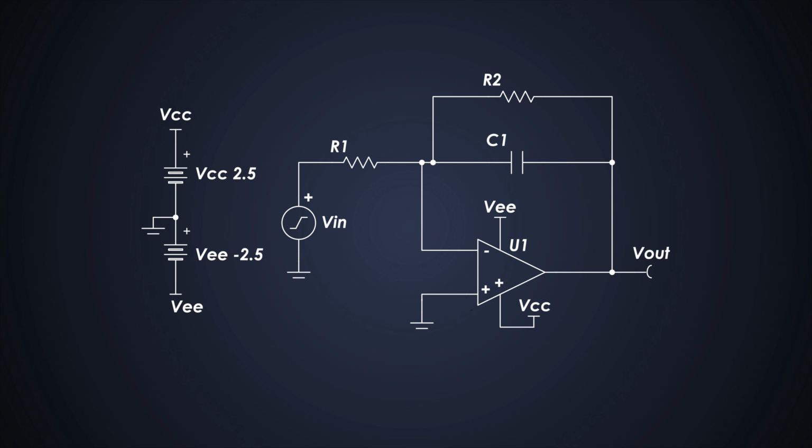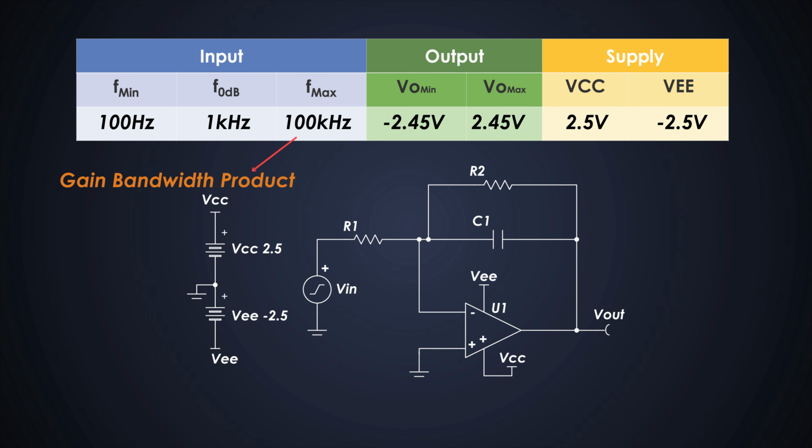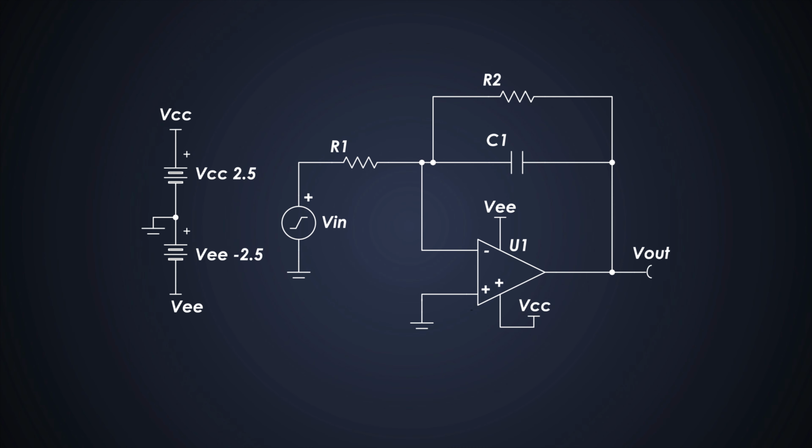There are a few important points that we need to consider while making this circuit. We should select a CMOS based op-amp to minimize the errors from the input bias current. The value of this feedback resistor should be very high. The gain bandwidth product of the circuit will set up the upper frequency. And an adjustable reference voltage should be connected to the non-inverting input of the op-amp to cancel out input offset voltage, or else the DC noise gain will saturate the circuit.